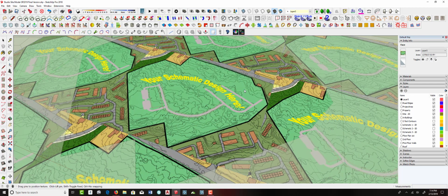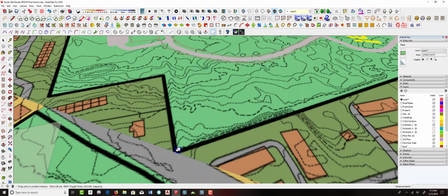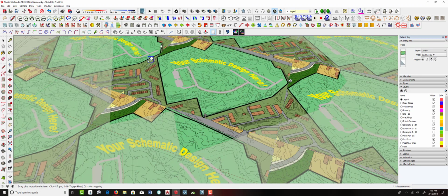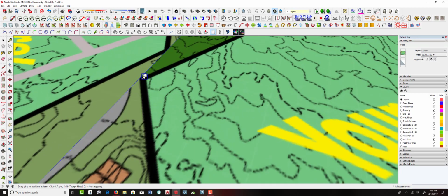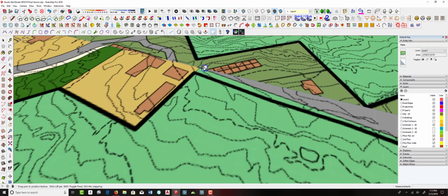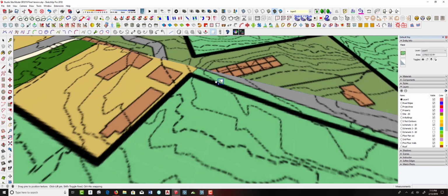In this case, since I know this is exactly the right proportion, I'm going to click, let go of the mouse button, place that there, click this, let go, place that right at the edge. That thick property line is visible, but it's thicker than the original line, so I'm going to put it kind of in the center of that if you think about the AutoCAD drawing. And this one, the property line in this case goes across here, but we're going to stretch the site out to the right of way, so that's what the geometry has.